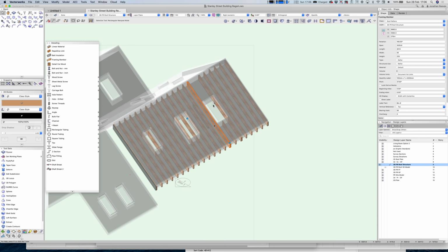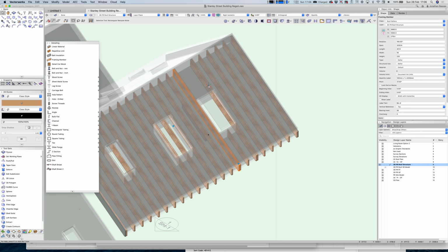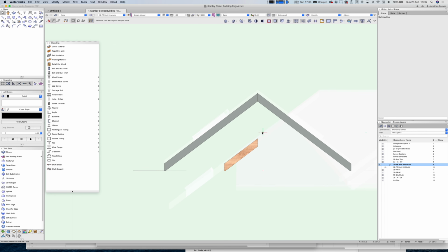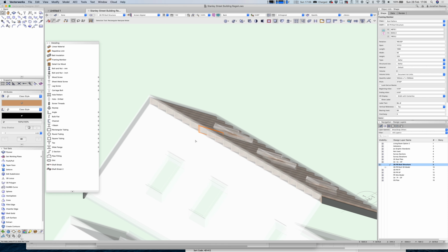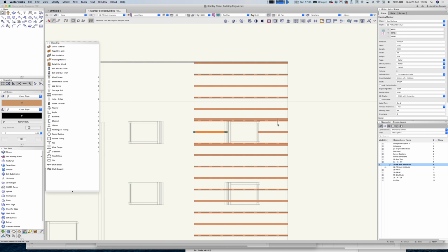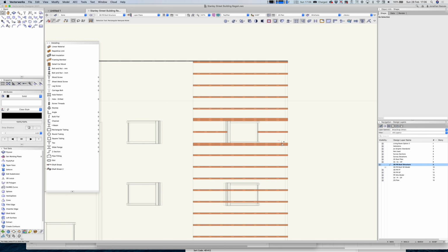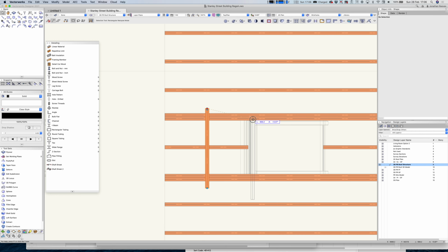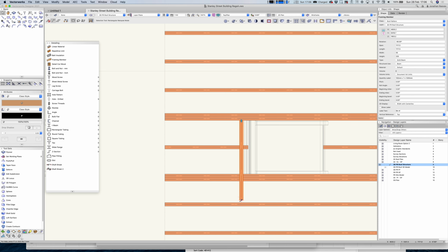Now you will notice that if you basically readjust the position of the rafters, because they're fixed probably from the bottom anchor point, the one that I amended at the top there is now vertically in the wrong position, but that's no bother. You just basically move it up and essentially drag it into position. That's excellent. Okay, good. So this is a nice little start. So what we'll do is now duplicate one of these rafters again. Let's just Command D, Command L. And basically I want to make this into basically a beam really, so it's got no pitch. So I'll just make it into a solid beam. So it's not a rafter anymore, it's really just a bit of timber that's spanning across.